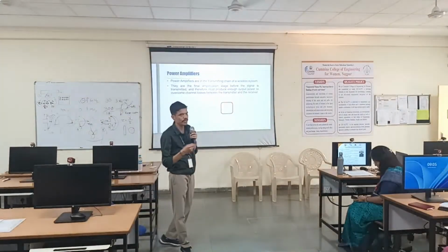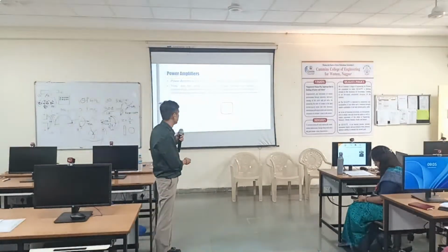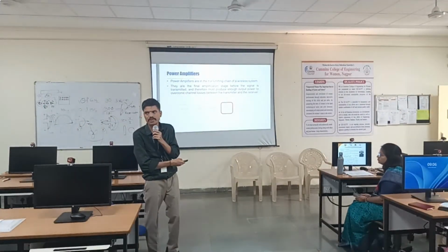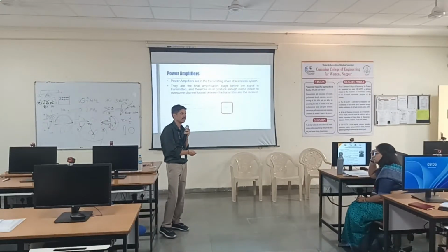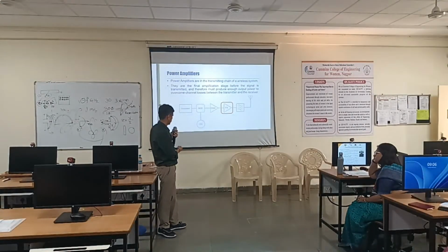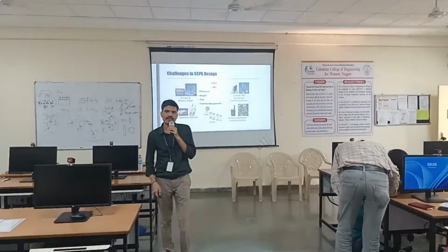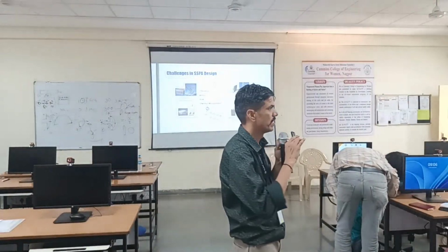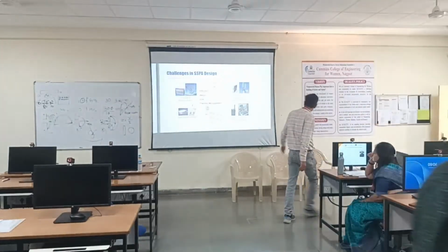This is PA, no need to explain. We already know that this is the last block of any transmitter just before an antenna. Something in between you can find always with the choice of band pass filtering. So depending on applications, we have different PA requirements. Somewhere we need higher efficiency, somewhere we need higher power, somewhere we need higher gain or output power.